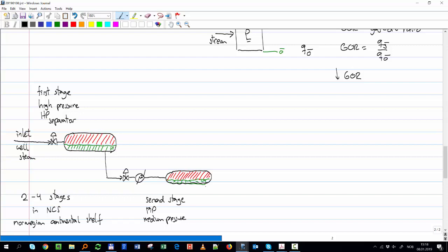Okay. After that, we are following just the liquid, what the liquid is doing. Let's make 3 stages only. Remember, sometimes I might need to have a pump just to flow. If the separators are far away on the platform, I might need a pump, but we don't have it just now. And then we have this separator, that's the most typical configuration, where I have high pressure, medium pressure, and the last one will be low pressure. Okay, very simple, low pressure. The third stage,